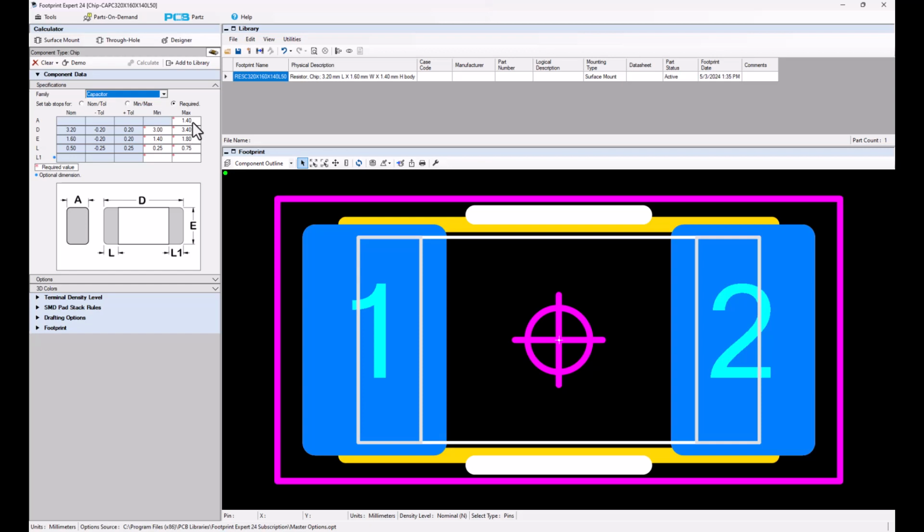And every time you change the height, since the height is in the footprint name, and it's also in the 3D model name, therefore you're going to have all kinds of duplicate footprint patterns, with the only difference being the package height. Or the difference might be the tolerance, the plus and minus tolerance.